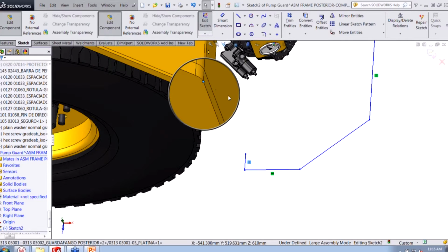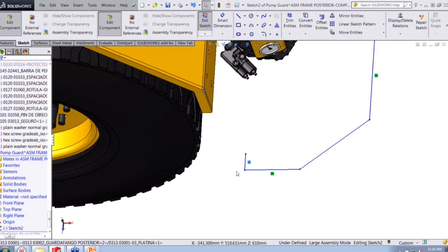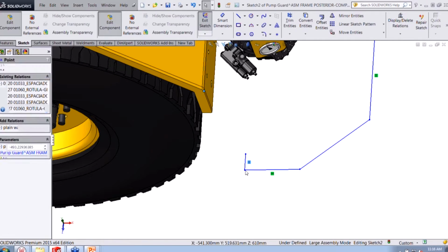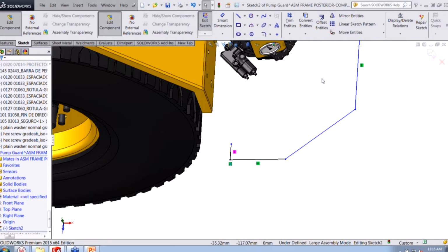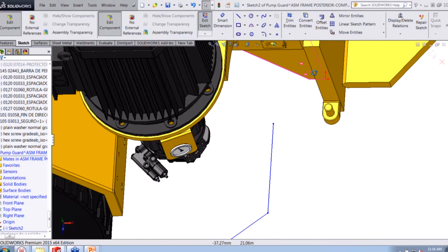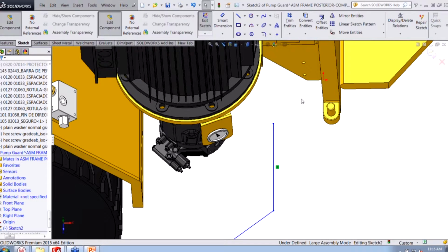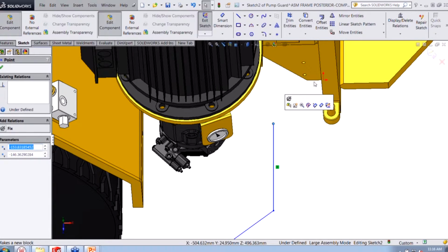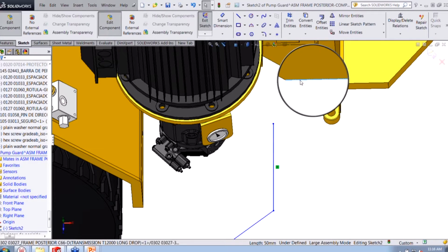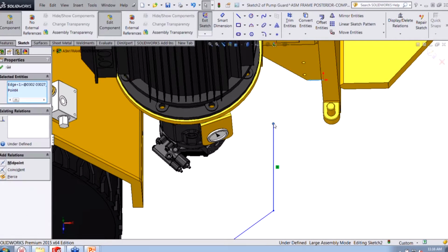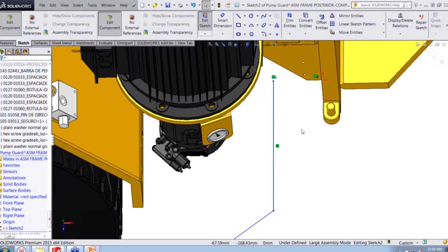Okay. Click escape to get out of my magnifying glass. Notice how it stays selected. And then I can select this point, and I can go ahead and make them coincident. So the G key is going to allow you to zoom in when, say for example, you're in a situation where you can't find something, like I can't zoom into that edge, I might lose where I'm at. I click on the G key, zoom in, grab whatever I need to, and grab the other entity, and then go ahead and make that coincident as needed. Okay?